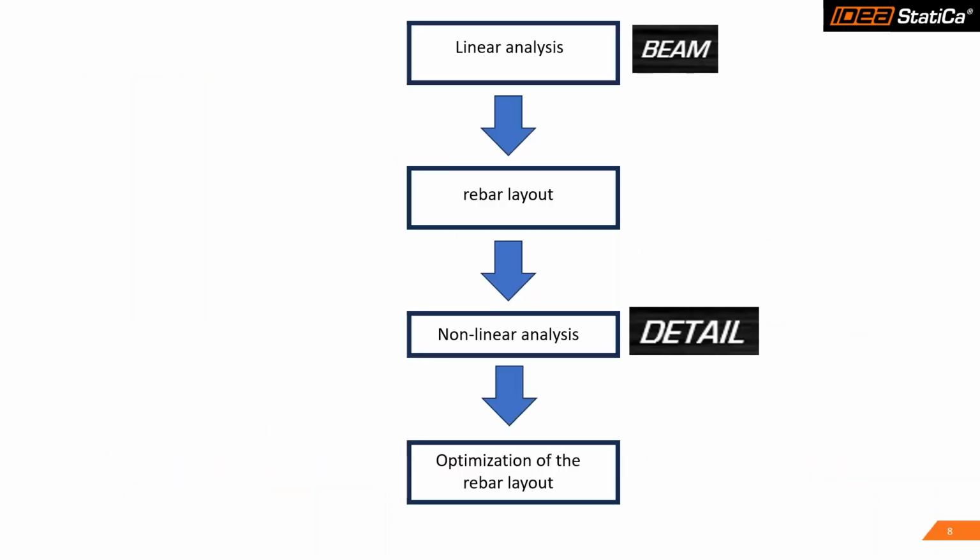Okay, another question is, how do I work with the program Detail? The first step is to conduct a linear analysis. With this linear, elastic analysis, you have to find the rebar layout, the necessary quantity of rebars or of prestressing steel, and thereafter all the challenging areas.